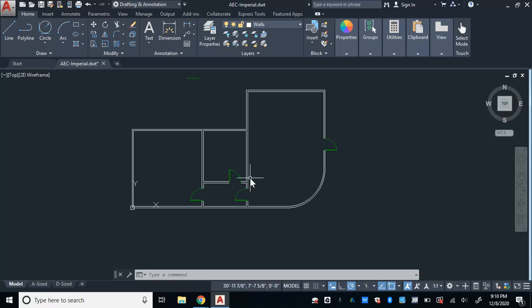Next, we have to deal with the windows. It states in the book, it says locate the windows along the wall using object snap tracking and track from the outside corner of the wall. For example, along the bottom wall, the first window on the left side is placed 2 foot from the outside corner of the building. When you position the first window along a wall, use the rectangular array to evenly space the others. For example, to place windows along the bottom wall, it tells you what the array command should be and things like that. And it also states that the column offset should be 6 feet.